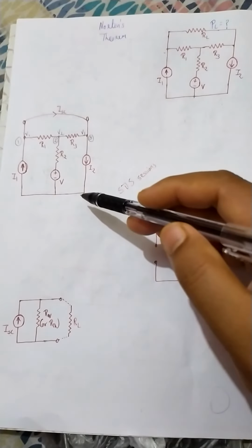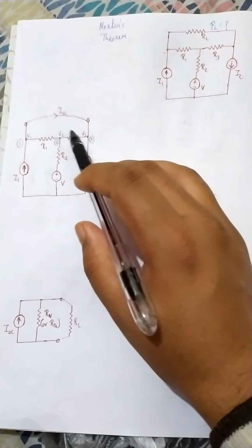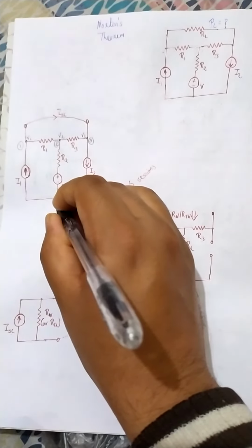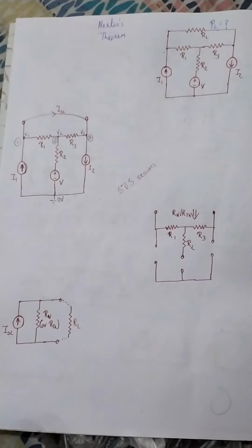You could think of this circuit as very similar to the circuit we discussed while applying Kirchhoff's laws. So we apply nodal analysis to find V1, V2 and V3, short circuiting and assuming this node to be at zero potential.